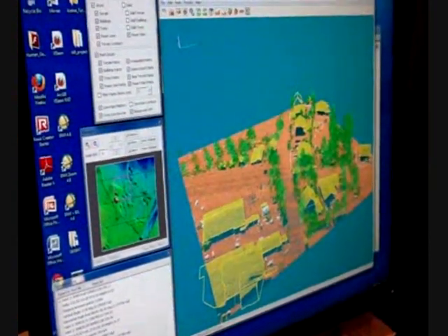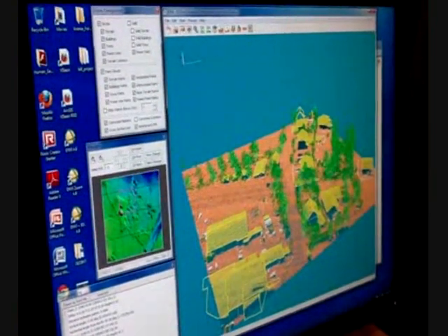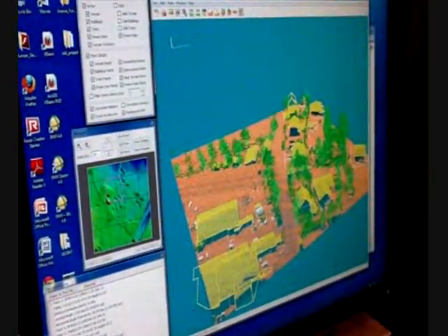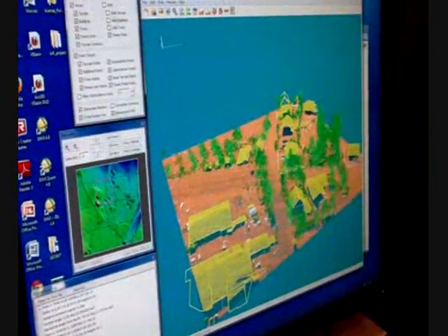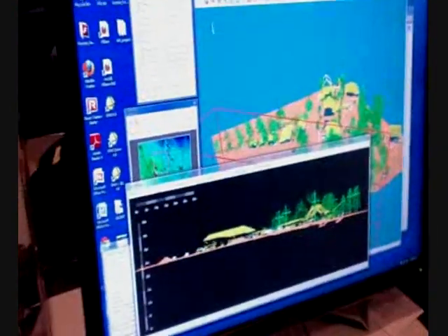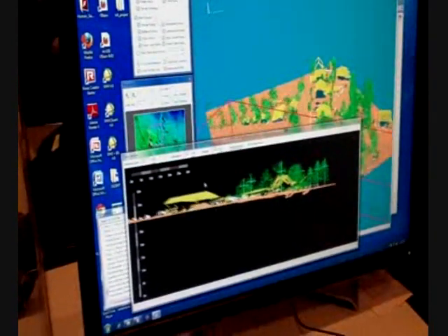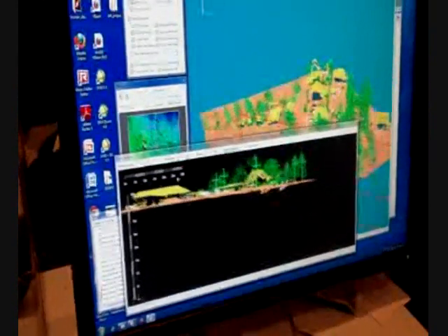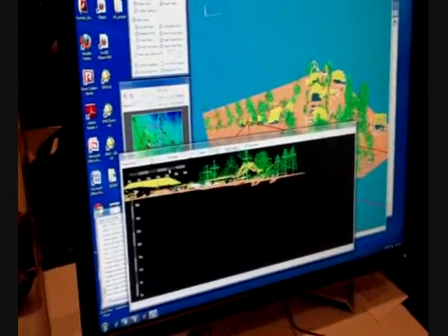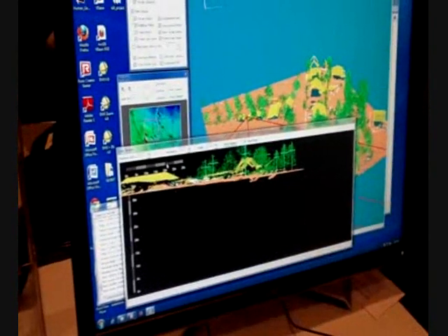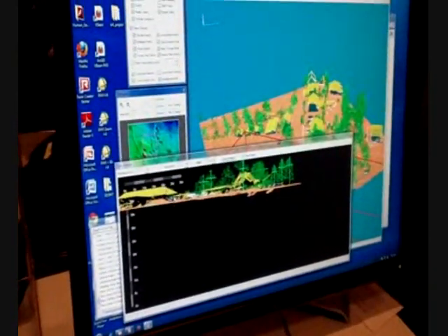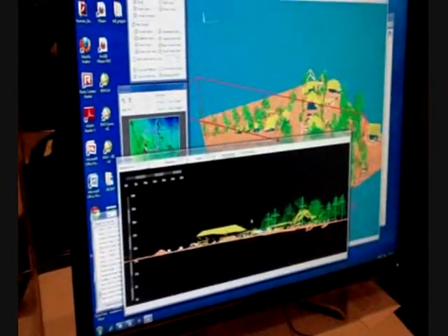If you want to do a cross-section, select the cross-section tool, draw a line through a region here and click. Then in the lower bottom area, I have a cross-section view rendered in the black area. If I move within this cross-section window, I can actually manipulate the point cloud. And if you want to see the top of that roof, it's just over 20 meters in height.